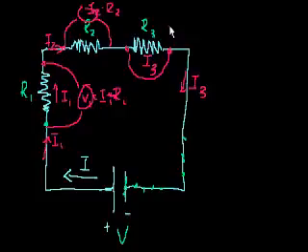But anyway, if we look at the voltage from here to here, it is going to be I3 times R3. So what we see is that the voltage across the entire circuit, which I can write as V total, is going to be equal to the total potential drop across each of these devices. So let's think about the electrons.